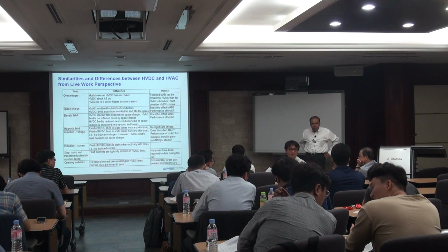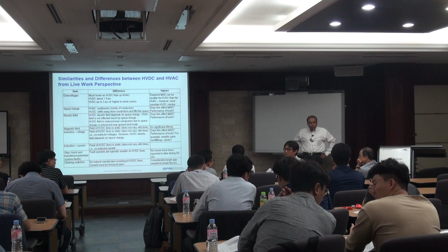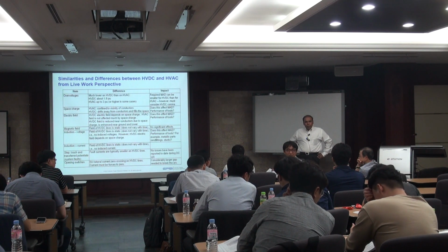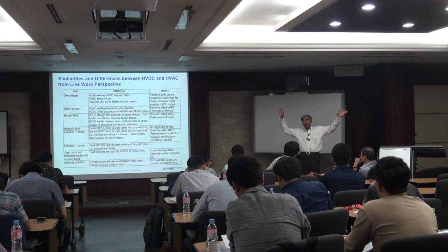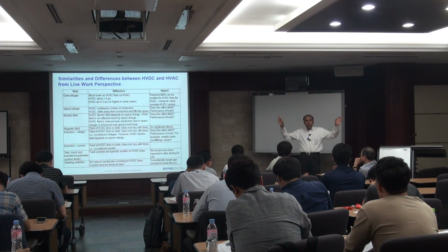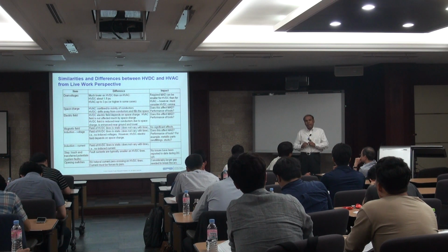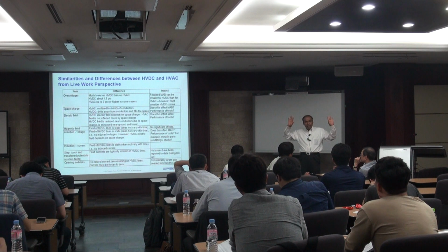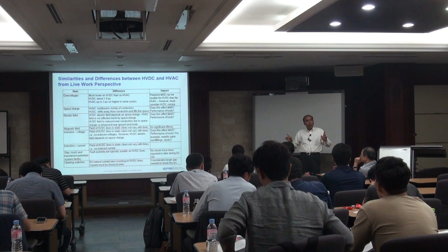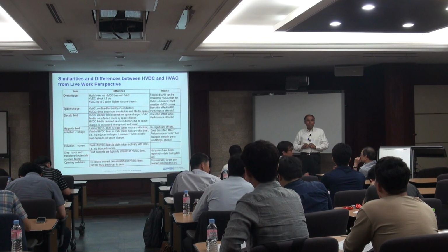If you think of DC lines, weather is good, no rain, there won't be any corona. That's not correct. In DC lines, you will have a fair weather. We call it FAIR. Fair weather means clear, sunny day, nice, everything. You still have a corona issue with the DC lines.